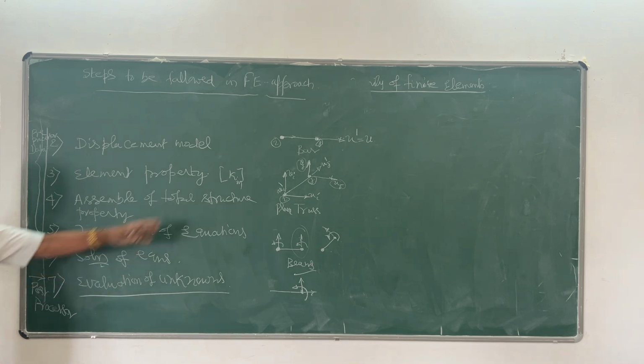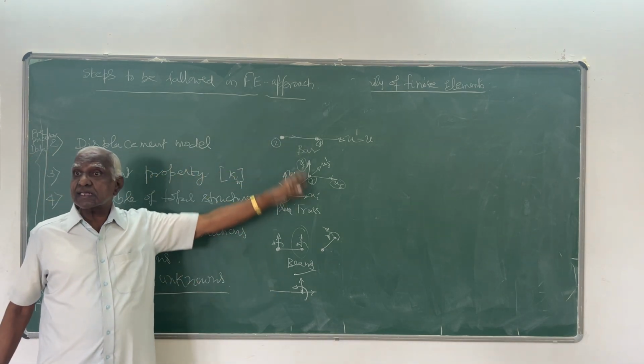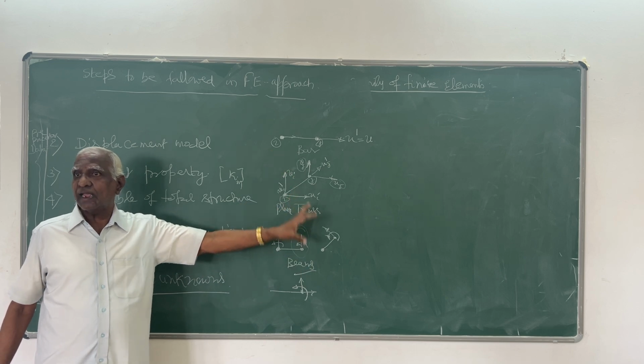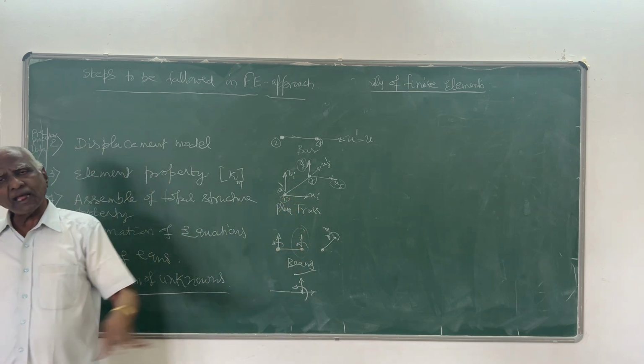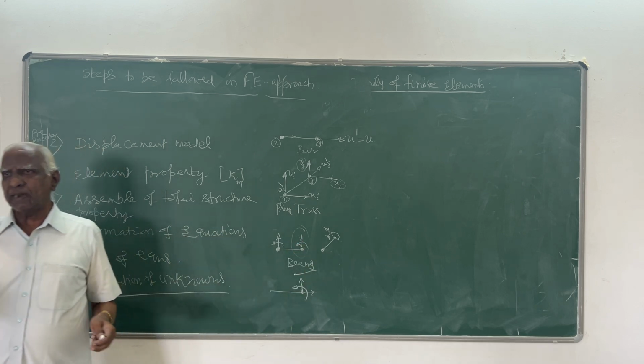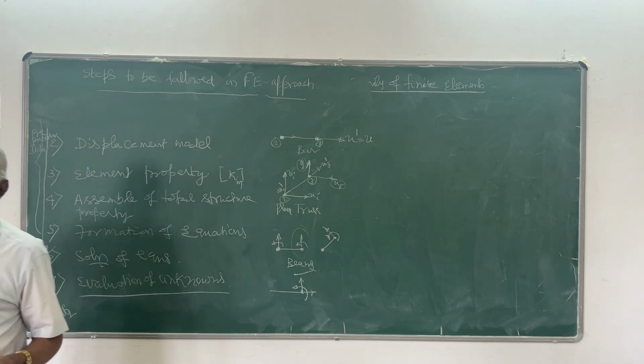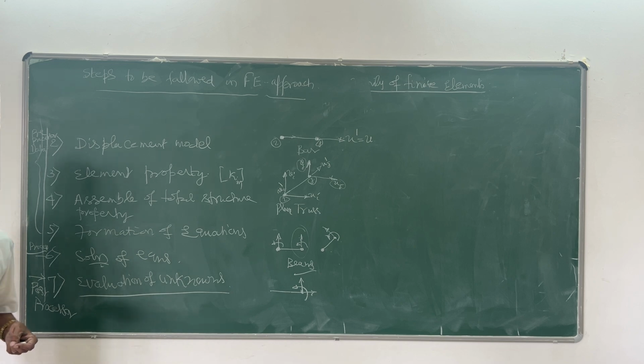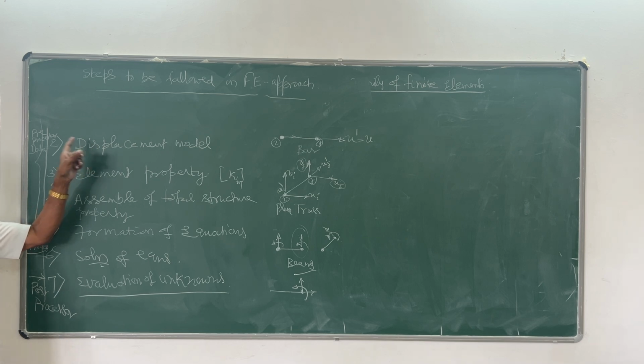Now I am talking about degrees of freedom for element nodes. Like that, in the other 2 dimensional cases also, depending upon plane stress, plane strain problem, or axisymmetric problem, or usual 3D problems, you have degrees of freedom. For those degrees of freedom, which are possible movements, either translational or angular, you have to choose a suitable model.